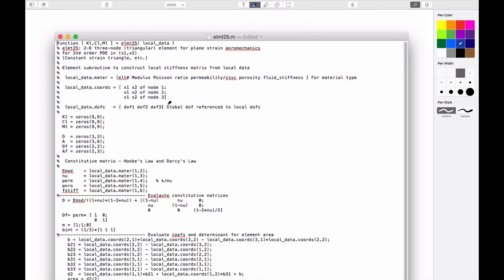And so you'll remember that if we want to get an expression that represents an element which happens to be a triangular element, then the way we'd put that together would be in terms of the coordinate system, whereby we'd have a displacement at node 1 in the x direction, a displacement at node 1 in the y direction, and fluid pressure at node 1.